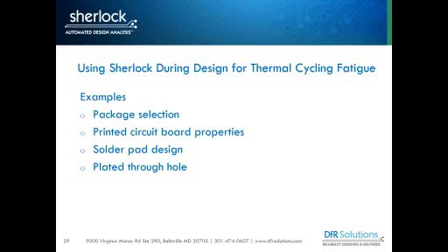If I see copper fatigue on other leads during thermal cycling, it's very rare. It does happen, like some large pin grid array components. We have seen lead fatigue, especially on a very large pin grid array. But it has to be sort of unique. We're talking like a 50 millimeter pin grid array on a very thick FR4 type of circuit board where you're actually getting large distance neutral point bending of the pin grid.